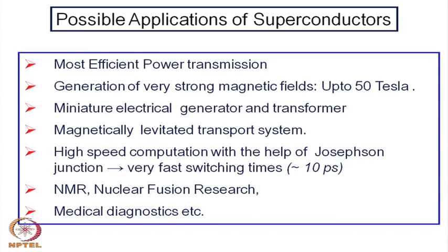If you want to use low temperature superconductors, we need a cryogenic system where liquid helium has to be fed into the system. Without liquid helium one cannot get superconductivity of the low temperature superconductors, whereas for high temperature superconductors it is possible to use liquid nitrogen, which is much cheaper, and that was one of the driving forces for increasing the temperature.